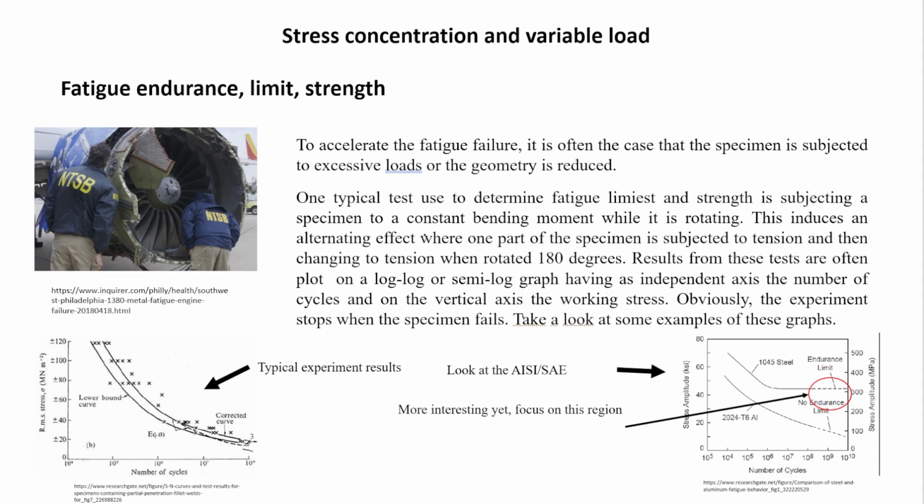Now we have seen that it fails, and then yeah, you cannot do a test for 30 years, but you can speed up those tests by applying certain mechanisms and strategies. Then we can enter to talk about what fatigue endurance is, how it is determined, and everything. And let's see. When we talk about fatigue endurance or fatigue limit or fatigue strength, I'm going to use that interchangeably along the whole presentation. It is a value that comes from testing.